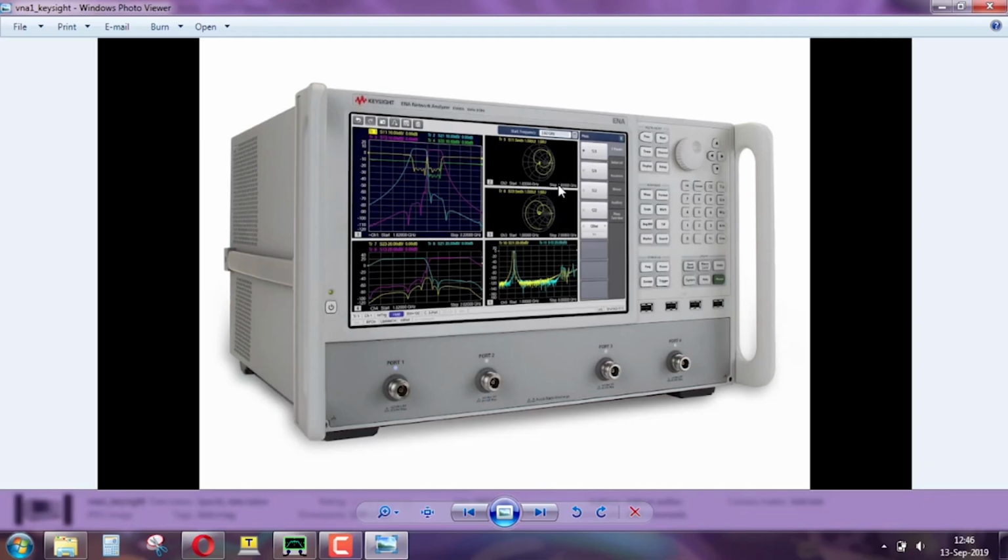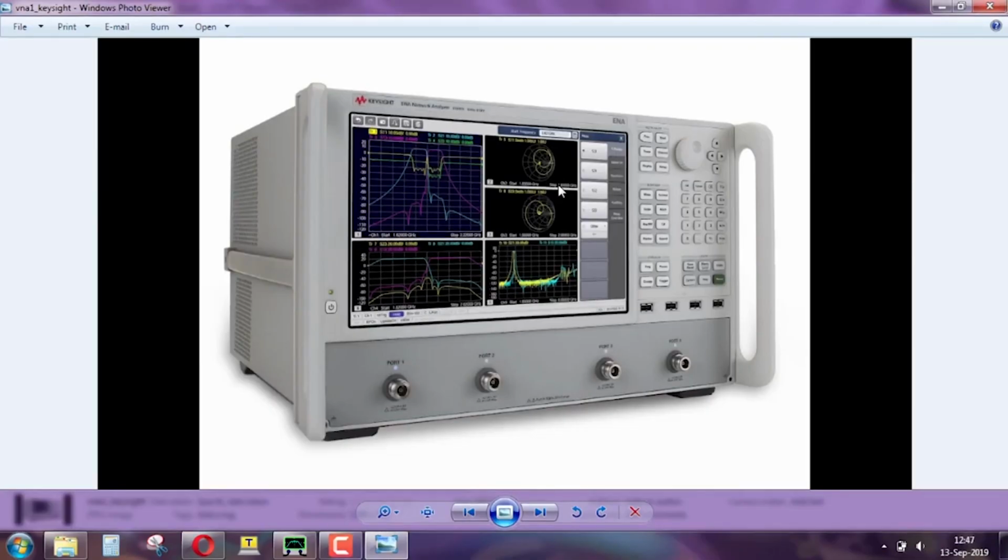The hardware nowadays comes with the ability to plot impedances on a Smith chart. You would connect a cable to this, then a device, and maybe some termination. On the Smith chart you see what impedance is seen. It can be used for a variety of purposes, with very high capabilities. They can go up to maybe 18-20 gigahertz, whereas the cable that we have is no good for more than even a gigahertz. So, you need to use specialized cables for them, and these are wonderful equipments, temperature stabilized, etc.